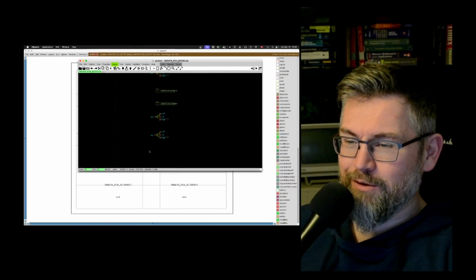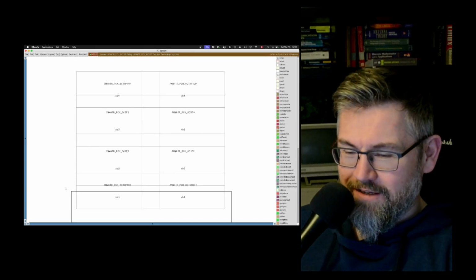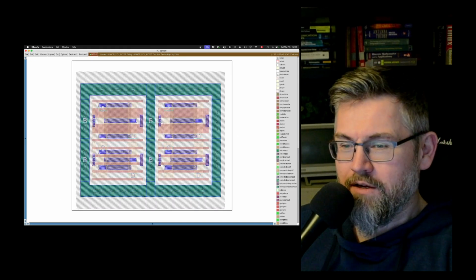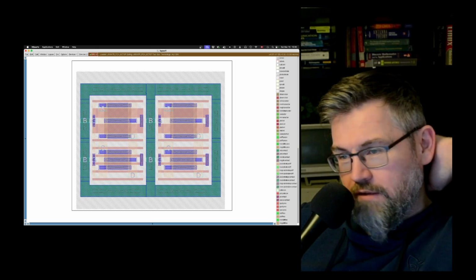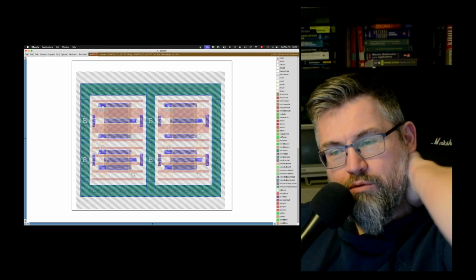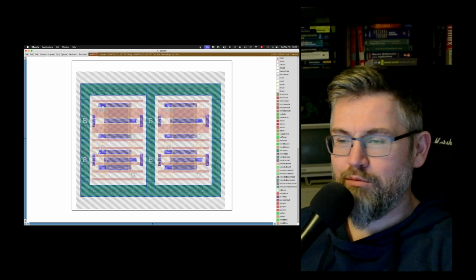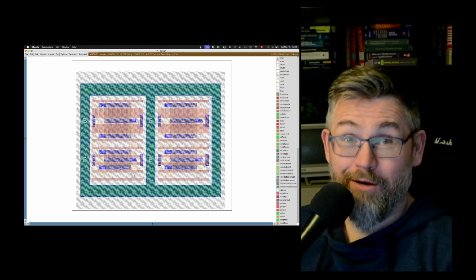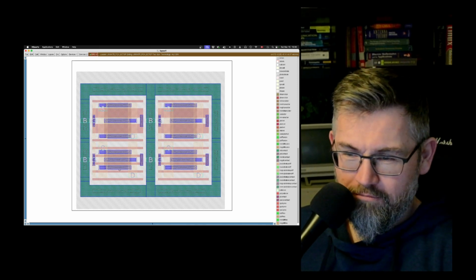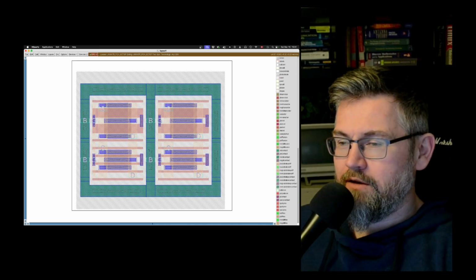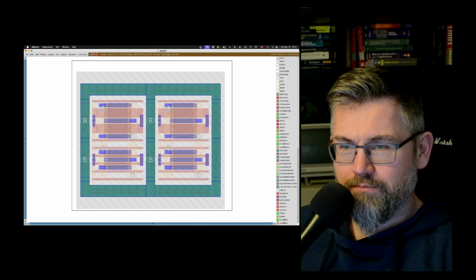Yeah, they're all PMOSs. Anyway. So anyway, you can see that they have the same size. Although they're different gate length, they have the same size. And that's just to enable, let's say, automatic routing, which I haven't really completed yet. But anyway, the standard size transistors.